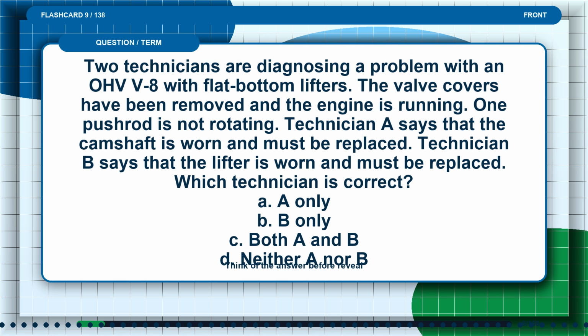Flashcard 9. Two technicians are diagnosing a problem with an OHV V8 with flat bottom lifters. The valve covers have been removed and the engine is running. One pushrod is not rotating. Technician A says that the camshaft is worn and must be replaced. Technician B says that the lifter is worn and must be replaced.